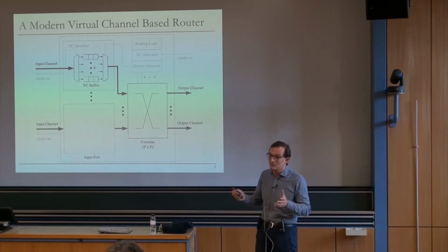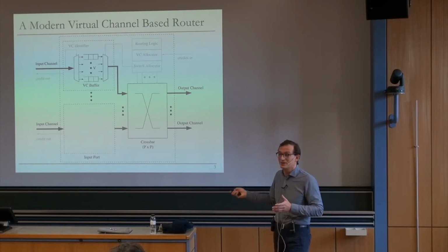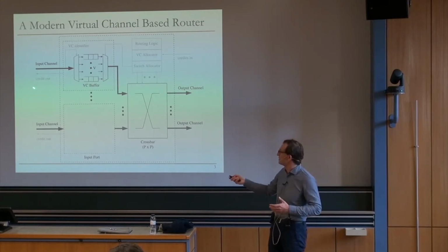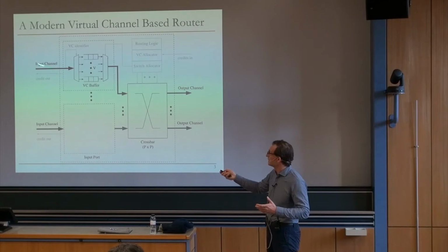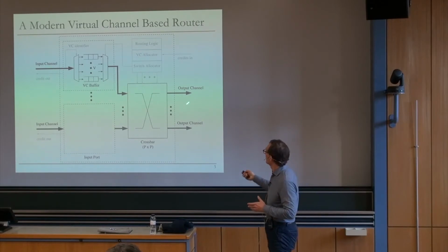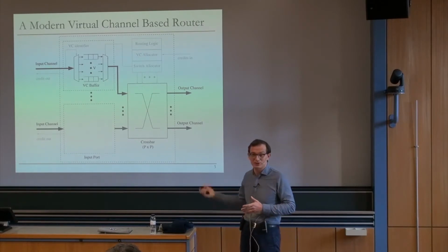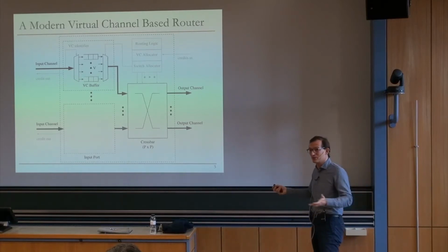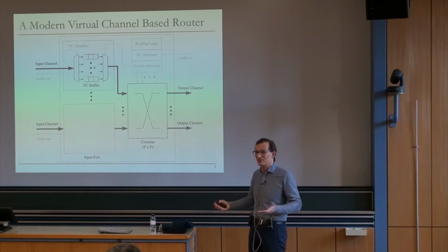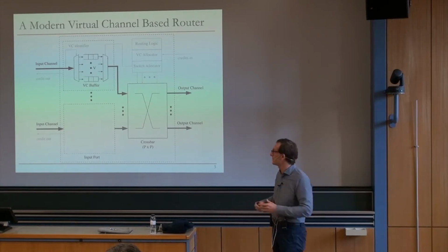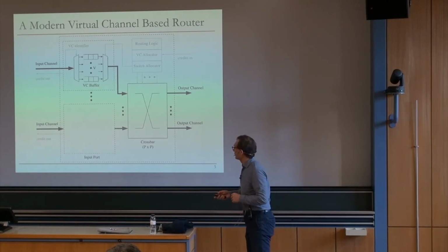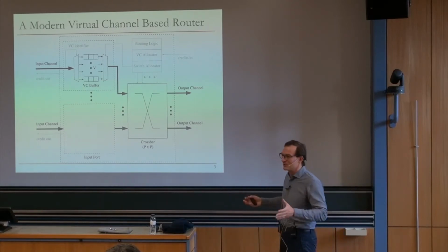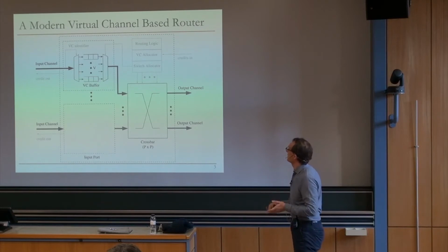Because if you think about it, in an out-of-order processor, you need to have something like this also, right? You need to have this sort of network to distribute an instruction from a particular place that you fetched it from into the corresponding functional unit that it wants to go to. And the functional units could be heterogeneous because you don't necessarily go to every functional unit. An add doesn't go to a divide functional unit, for example. Okay, so this is really nothing new in that sense, but it's new in the sense that the way it's built is a little bit different.